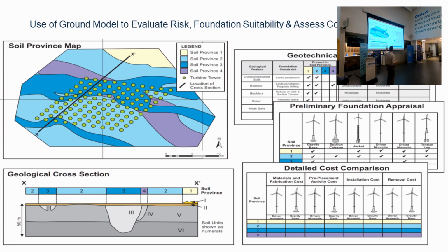And so I guess a traditional approach to this is integrating your geophysical, your geological, and your geotechnical data, and creating soil province maps that laterally demarcate areas of similar vertical soil conditions. So for example, here you might have a soil province which is mostly representing the infill within a channel, which would be quite distinct from somewhere outside of that.